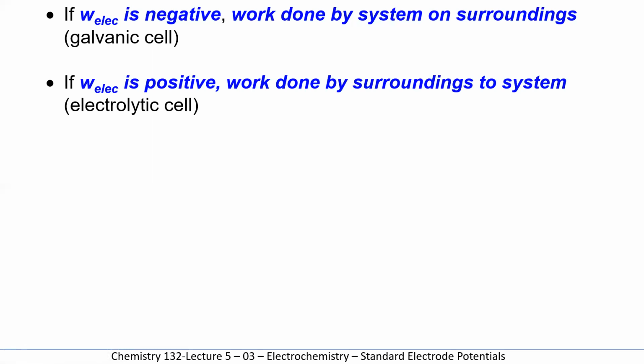An example of that would be the manufacture of chlorine gas from sodium chloride, a very common industrial process, because chlorine is a very useful oxidizing agent in cleaning water. We can mass produce chlorine from electrolytic cells that use electricity to drive the reaction in the reverse direction. Salt, of course, sodium chloride, is abundantly available all over the world. Wherever there have been ancient seabeds that have evaporated, they have left behind large deposits of sodium chloride, mixed with other chlorides, of course. And we can use electricity to drive that chemical reaction and change the chloride ion into chlorine gas.